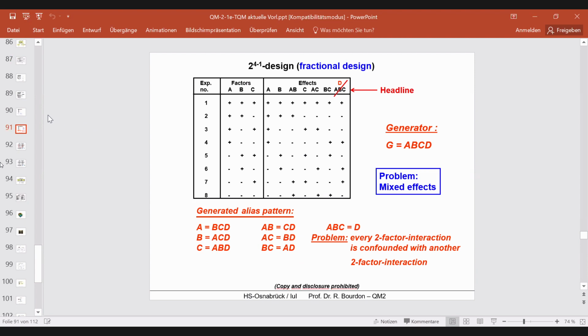The best is to take a variation of the 2^3 experimental design for the variations in a DOE. Taguchi proposed to take more than 3 factors in a 2^3 plan. He said, okay, the 3-degree interaction may be not so significant, maybe unimportant. And then he puts a fourth parameter D on this column of the interaction.